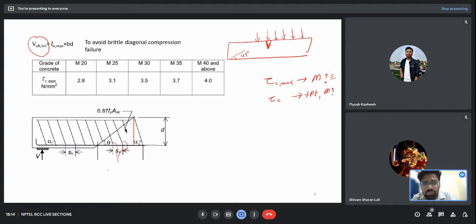You all know we have studied the provision of flexural reinforcement at the bottom and at the top. Those flexural reinforcements were provided in the form of Ast1 and Ast2. But here, please remember the stirrups are provided in the form of spacing. That is, we decide the spacing between two consecutive stirrups, and based upon that spacing, we provide stirrups throughout the beam.